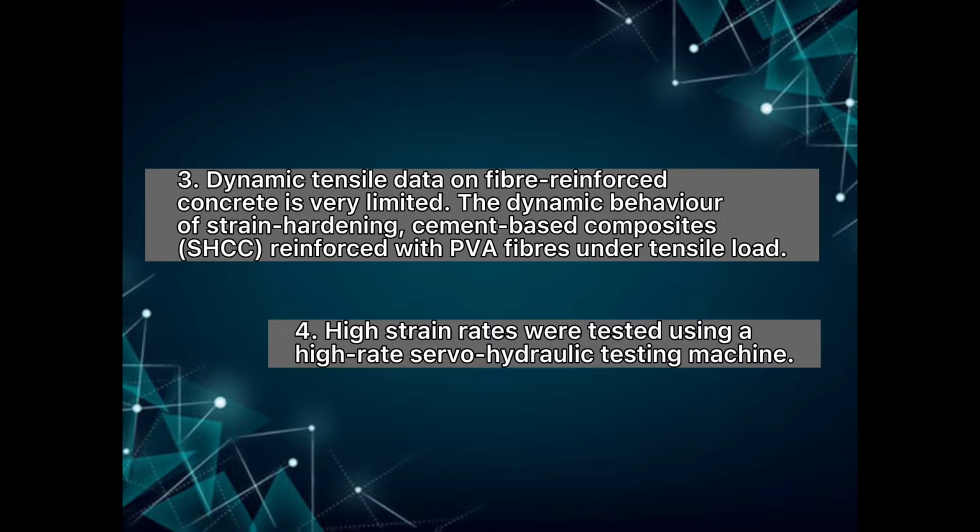High strain rates were tested using a high rate servo-hydraulic testing machine. The effect of the addition of short fiber on the static and dynamic response of TRC was investigated, and the microstructure of both composite and fiber was observed after the test using ESEM. An increase in tensile strength, strain capacity, and work to fracture was observed for strain rate up to 0.1/s with increasing strain rate.